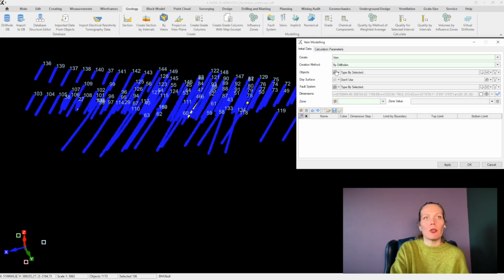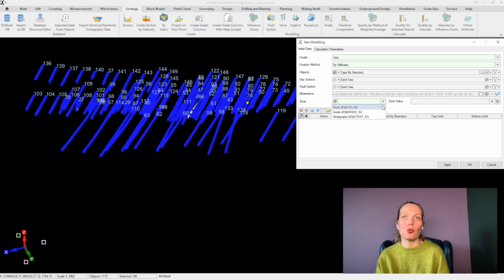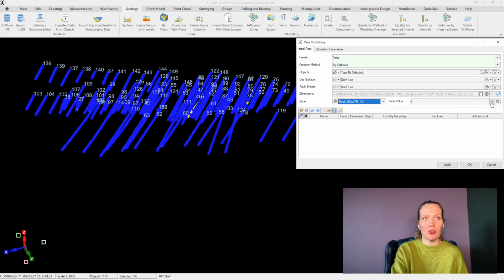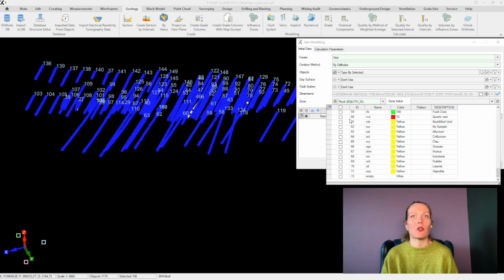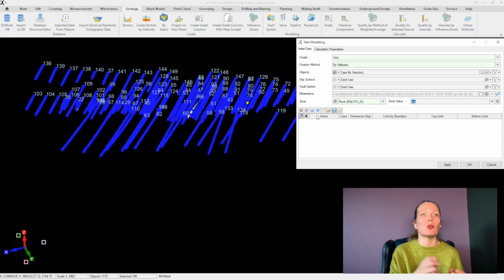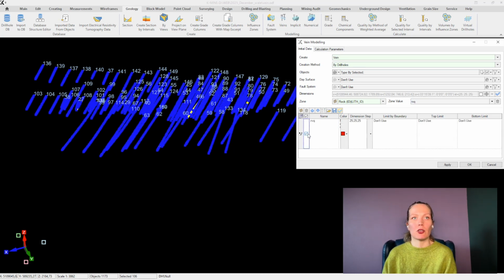And it also reflects how modeling software handles scale, different data types like drill hole samples, and modeling parameters such as triangle size or snap tolerance. All of this influences model realism, from small mineralized shoots to large structural systems. So in practice, this means managing multi-scale detail from broad fault systems down to individual ore shoots while maintaining consistency in geometry and grade distribution.